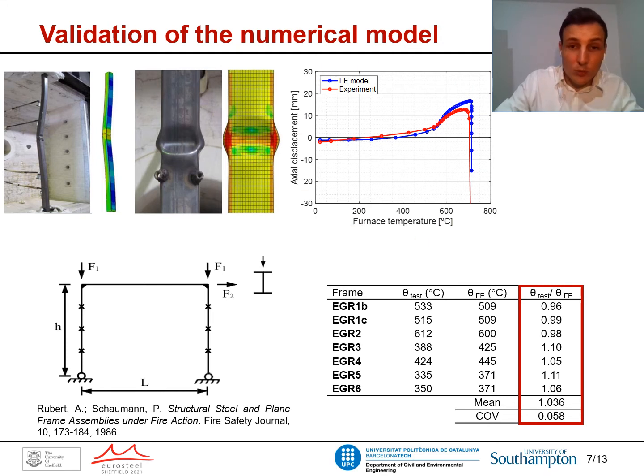But since we wanted to analyze the response of stainless steel frames under fire, we looked up the literature for laboratory tests of steel frames under fire. The most relevant one is the one conducted by Robert and Schaumann in 1986. They tested a total of 18 carbon steel frames with different geometries and loads applied. For this study, we only reproduced the one-bay frames.